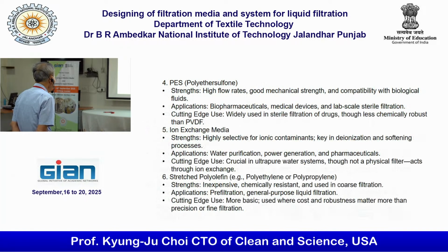The PES, polyether sulfone, this is a high temperature polymer they call it, but not compared with the PTFE. Yeah, good mechanical strength and application in pharmaceutical, medical, and lab scale sterile filtration. Sterile filtration, though less chemically robust compared with the PVDF. As far as the nominal membrane media, there are some available, very expensive. Crucially, in ultra pure water systems, they do use some ion exchange media, though not a physical filter, the ion exchange.